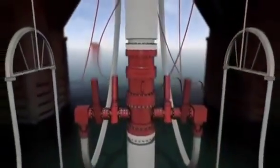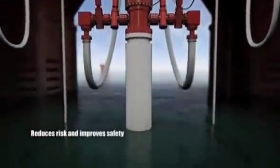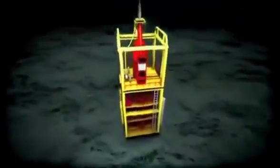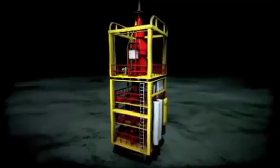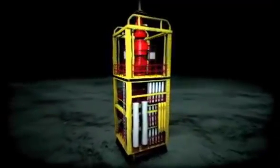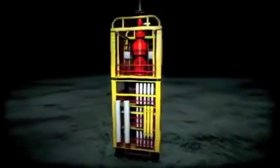Equally important, pressurized mudcap drilling reduces risk and improves safety because pipe can be tripped and rotated while fluid is pumped down the annulus. Gas percolation and bottom hole pressure are quickly indicated through observation of pressure differences between the reservoir and hydrostatic column, and simply managed by adjusting an annular fluid cap.